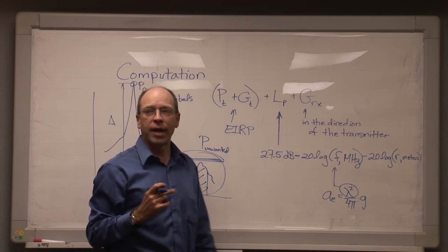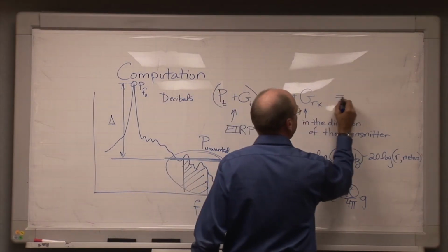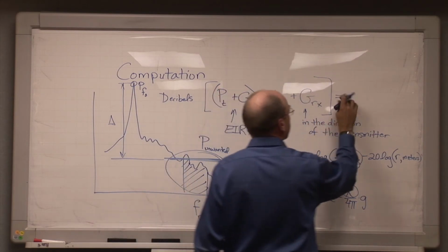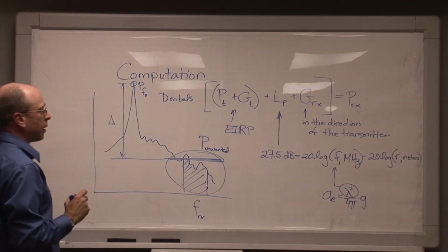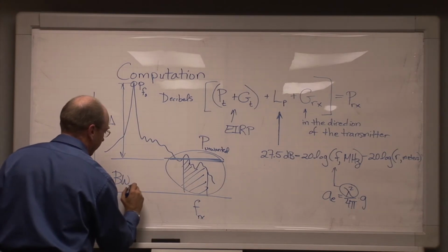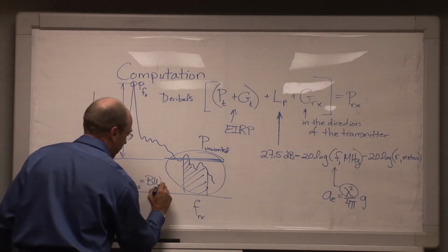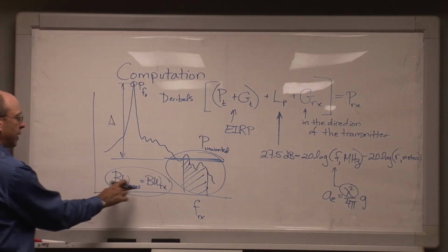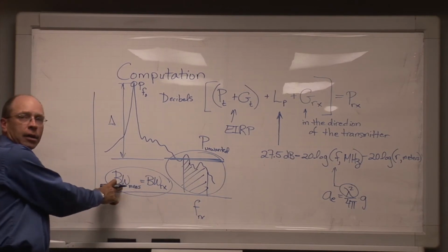We might have to do a little antenna pattern measurement, or we maybe can get an antenna pattern, or sometimes you can just estimate, at least somewhat closely. And all of this taken together is going to give you the power that's being picked up at the receiver. And this is where, by the way, having matched the bandwidth of the measurement to the bandwidth of the receiver is important, because we don't have to do any correction for the amount of power that the receiver is getting relative to the power being put out by the transmitter.